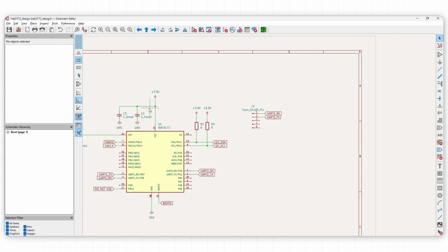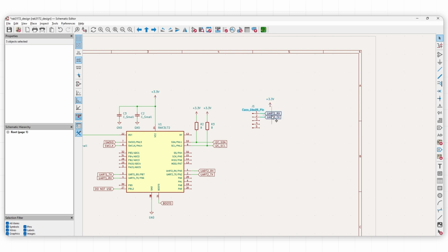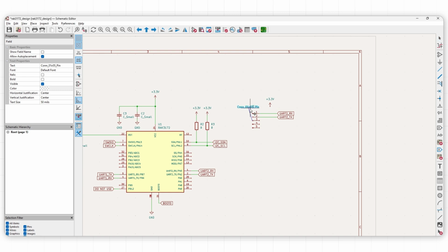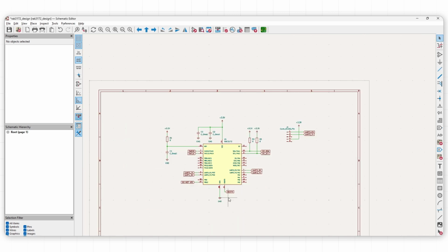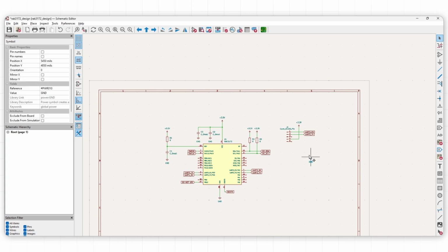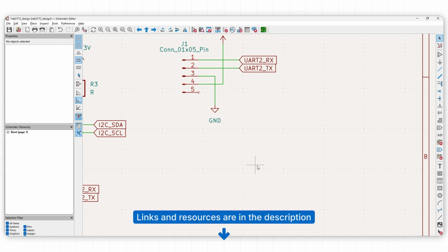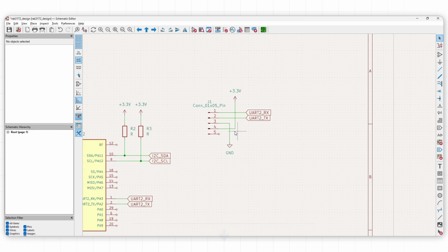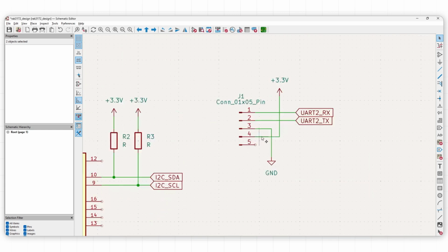If you are doing an RUI-free FW update, a boot pin is not needed. However, if you need to perform a full chip erase or need to upload the complete .hex file to your RAK3172 LoRaWAN module, you will need the boot pin to be pulled up, then use STM32Cube Programmer. We have a complete guide on how to use STM32Cube Programmer for RAK3172. This guide is very useful in scenarios where RAK3172 got bricked or went to a condition where you cannot use the UART2 RUI-free bootloader to update the FW.